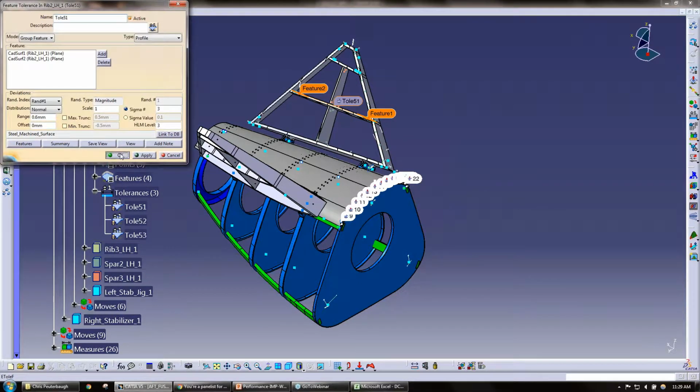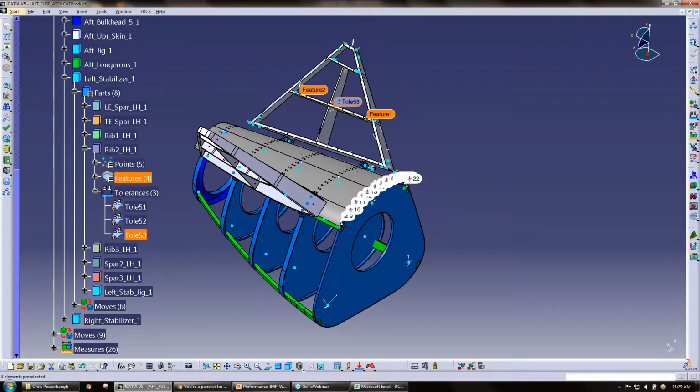It's also a good way to standardize your tolerances across your different modelers so that everyone's pulling the same tolerances for the same processes. So if you've got 5 or 6 different people that are modeling for you, you can make sure that they're all using similar tolerances on the same kinds of parts or the same kinds of processes.